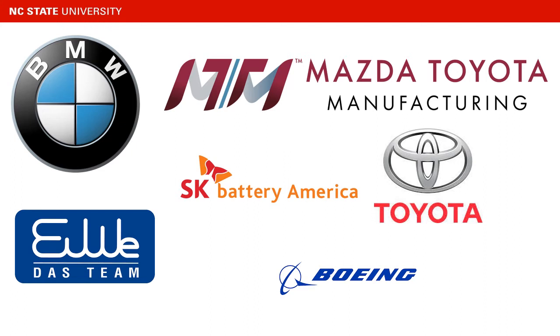The tests that I was able to witness and review on each of these sites included a field proof roll test and a laboratory Proctor test, which is used for specs by ASTM D698. The equipment used on site were sheep's foot rollers, smooth drummed vibrating rollers, and trench rollers for stormwater trenches and backfilling underground piping trenches. A proof roll is done by loading a dump truck with gravel and slowly driving over the area deemed for testing.